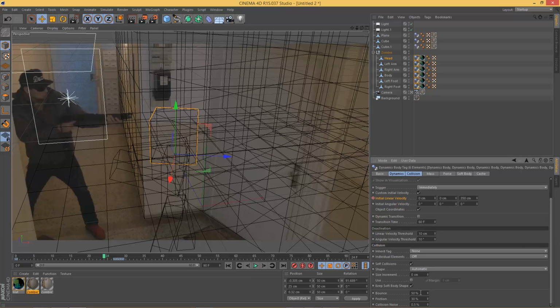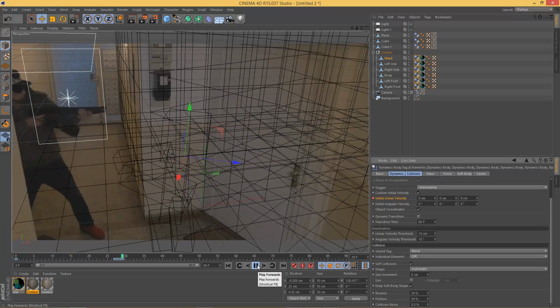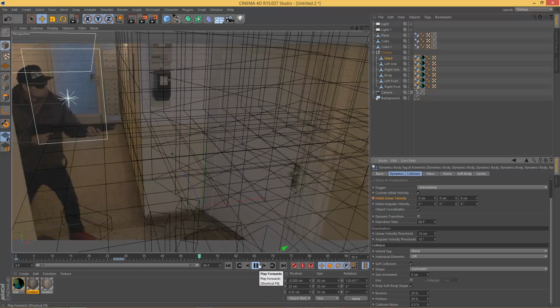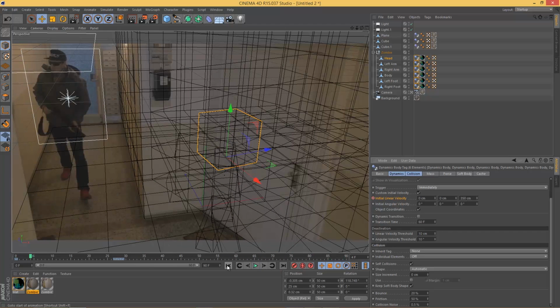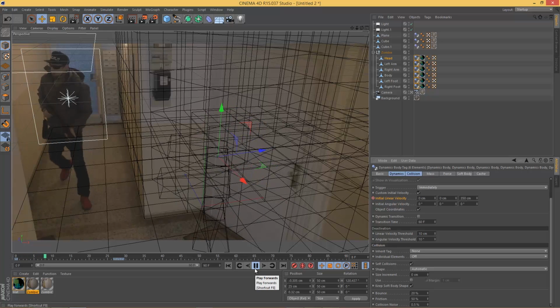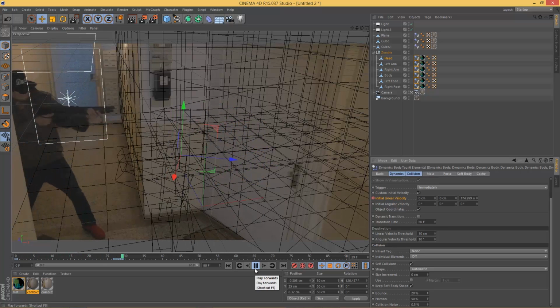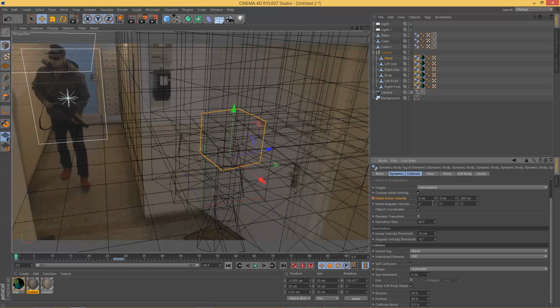And now go in and set the bounce to 20% and the friction to around, let's say, 50%. And then press play again. So it doesn't fly around too much, just moves backward but not bounces too much. And he's knocking that zombie off of his legs. That's nice. All right, one more time. Boom. For some reason, that arm is moving forward instead of back.